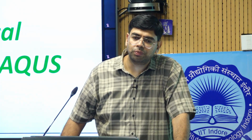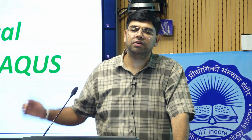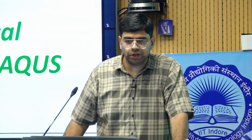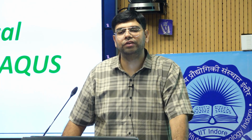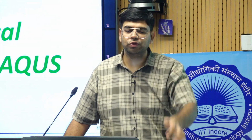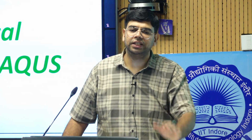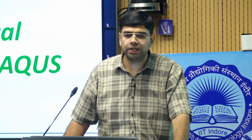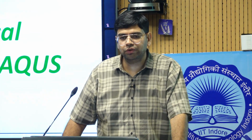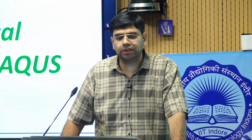Before going to the post-processing, you have to define what parameters you need to evaluate. For example, if you are conducting a simulation, what do we need to get? We need to get deformation, stresses, and strain. So these are the things we want to obtain as an output. So before going to the post-processing, you have to define that these are the parameters we need to evaluate after the simulation is carried out.